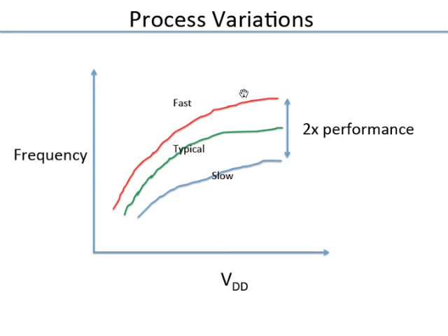This is the problem. So instead of doing worst case design, you can adapt, that means per chip you set a voltage which is suitable for that chip. Don't just say I'm going to use the voltage for the worst of this family of chips. Don't determine the voltage based on the black sheep in the family.